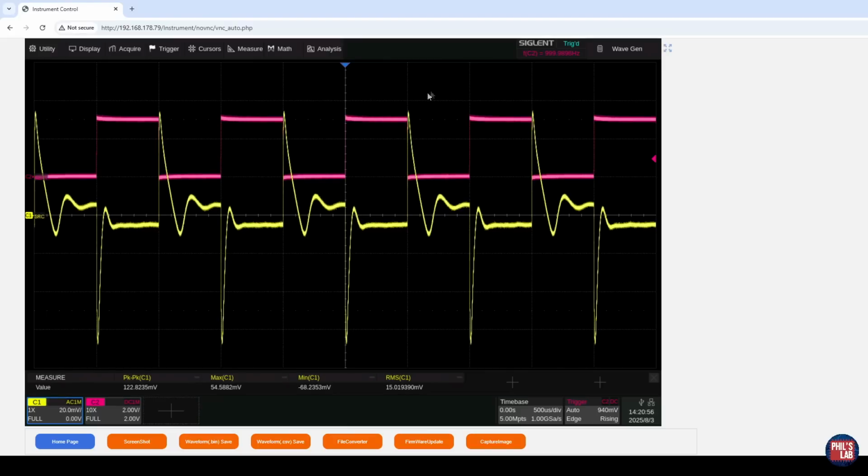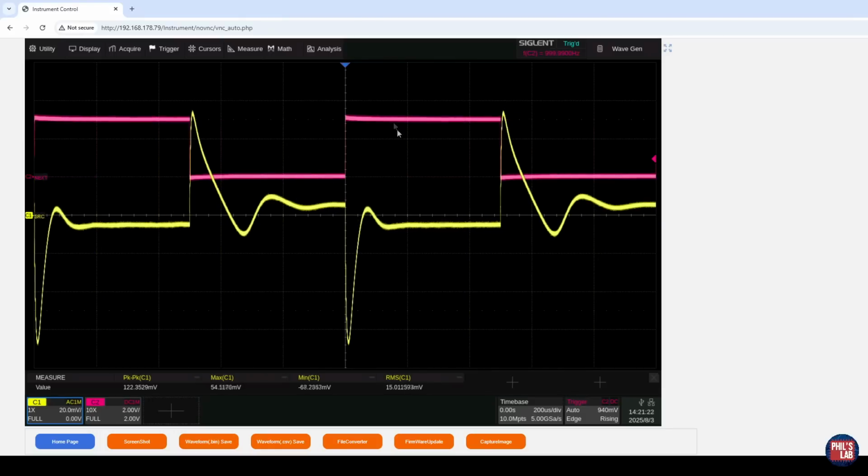But the square wave or the trapezoidal wave can be, of course, represented by a Fourier series of odd harmonics, and therefore we get a superposition of our impedance profile frequency points, and that then builds our impedance for this particular square wave. And here this again illustrates quite nicely that at a current demand, so the FET switching on where we have this rising edge, our voltage rail dips because now we have this increased current demand and our impedance is a certain amount, our series impedance of our power distribution network, and that's why we get a voltage dip. Before at DC, we settle back to 1.8 volts.